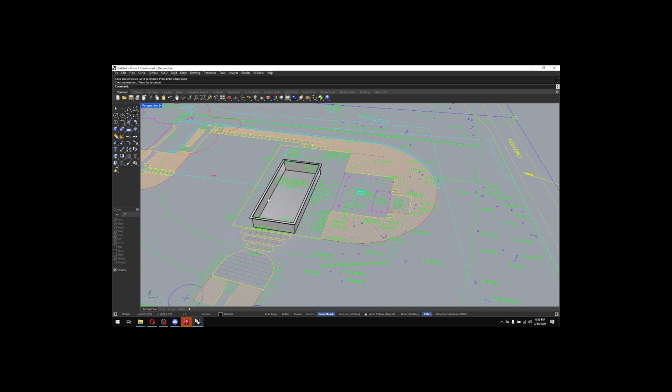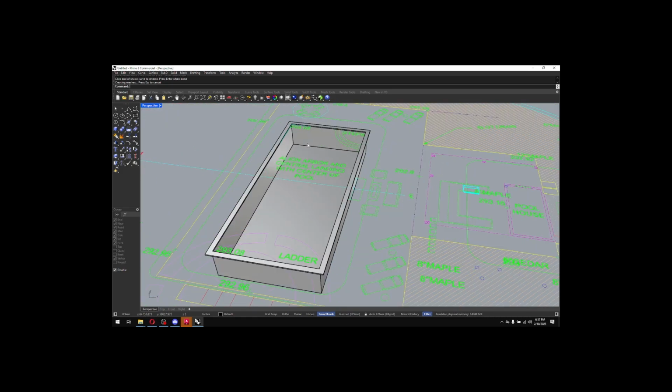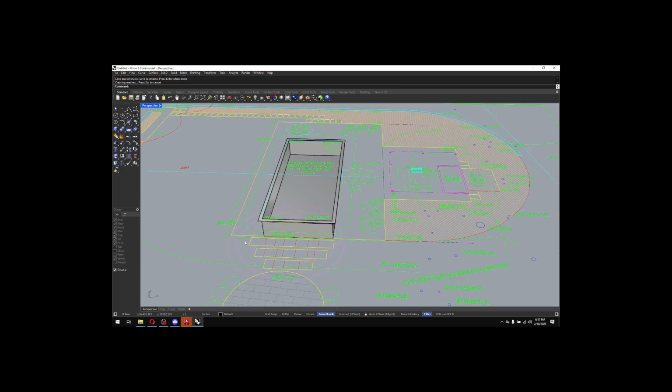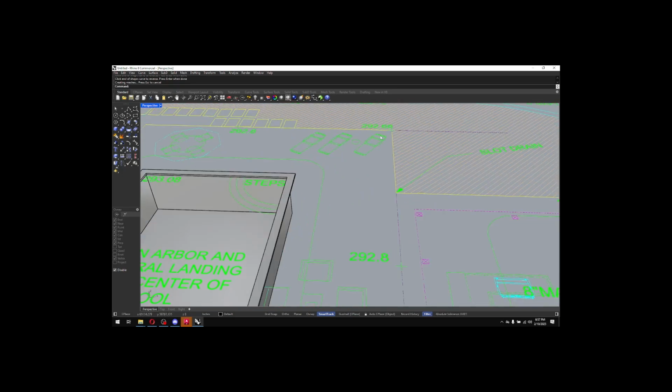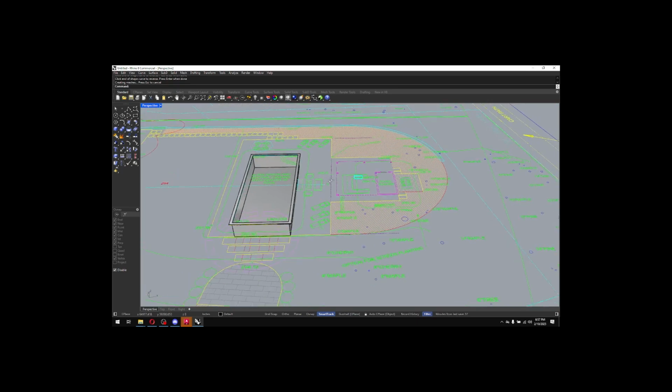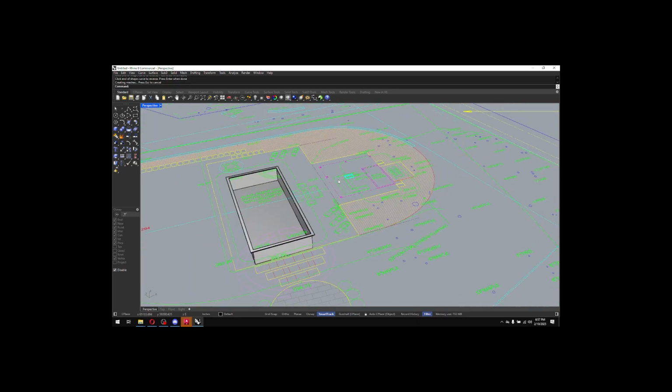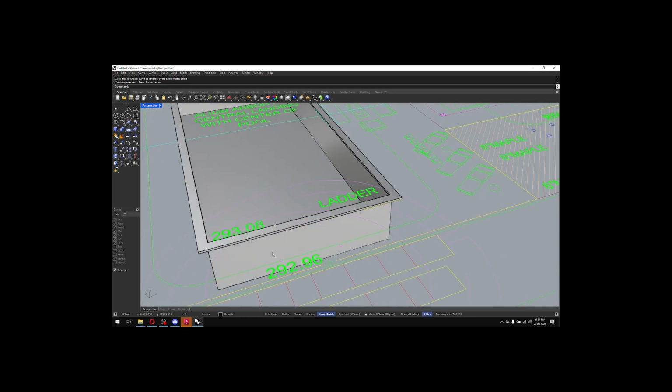When I'm building up a model like this, I'll build all my surfaces as simply as I can, based off of materials. So in here, I would have a layer for pool wall, a layer for pool coping, a layer for pool terrace, which is out here. Maybe we'll do that for the grading since that's somewhat quick. Pool terrace will be a different material. Lawn will be a different material, or a different layer. Anything that's a different material, new layer, call it something else. You're not charged by how many layers you have, so feel free to make as many as you want.